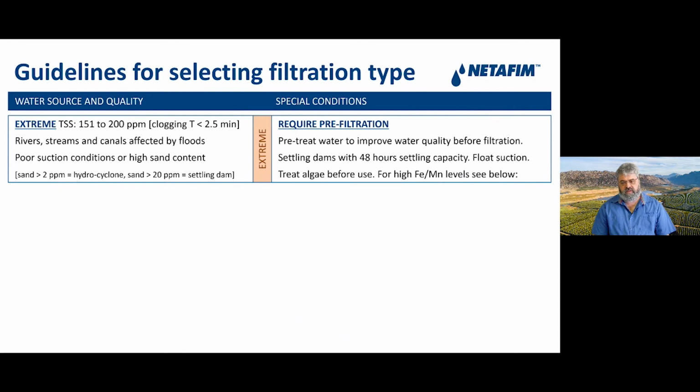If you go to settling dams, depending on what you want to protect, if it's something like a finer material than sand that is more like silt, then we need 48 hours of settling capacity.